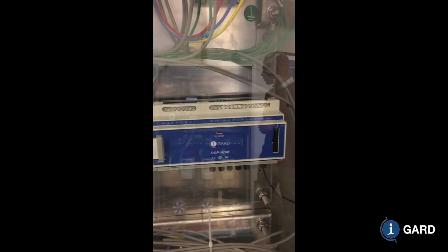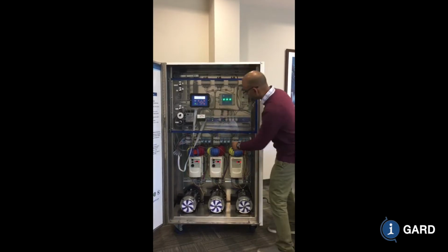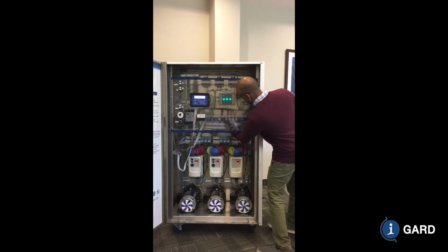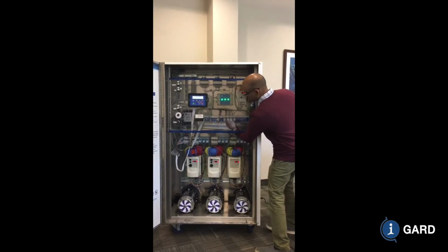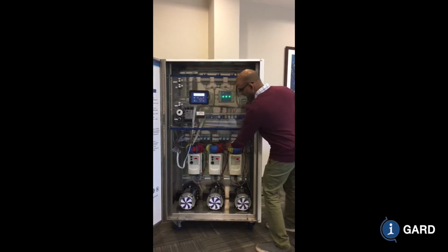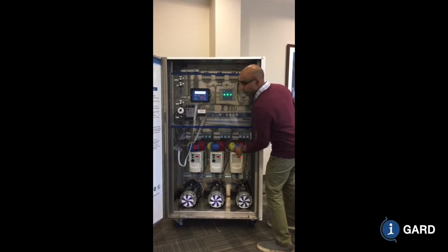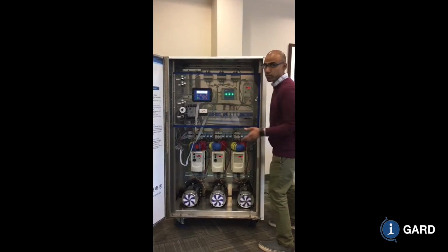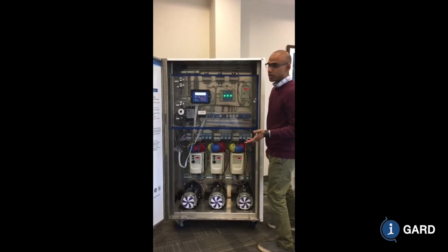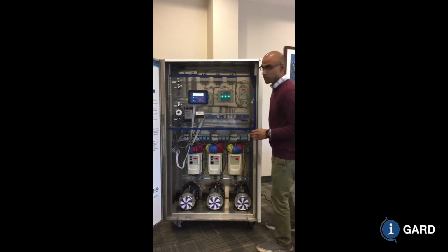So let's just go through our modules. The display module we have on front is connected to the power supply module, which is this one right here, and that's connected to the system module. And here are the feeder modules. The feeder modules are connected to your current sensors, which are looking at each feeder. The system module is connected to the DDR2, which is connected to the system bus voltages, to monitor the system bus voltages for the displacement that occurs on a ground fault. And the last module that we have here is the arc detection module, which is a new module that we have.